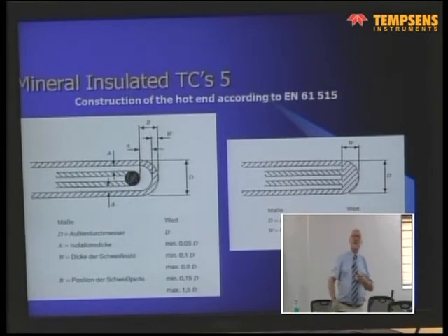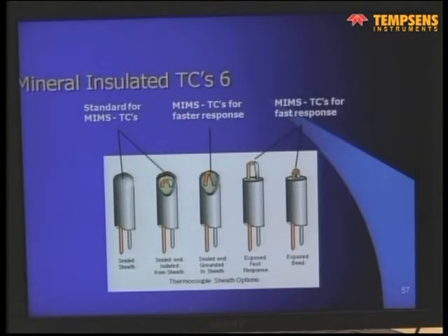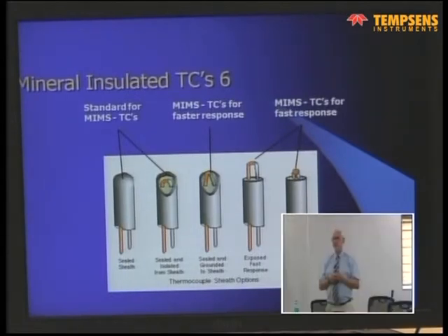The dimensions for the thermocouples in the case of being insulated are also in a standard, in an international standard. And so you also have other possibilities for your tip, outside the sheath or inside, depending on the application and on the required response time and whatever.